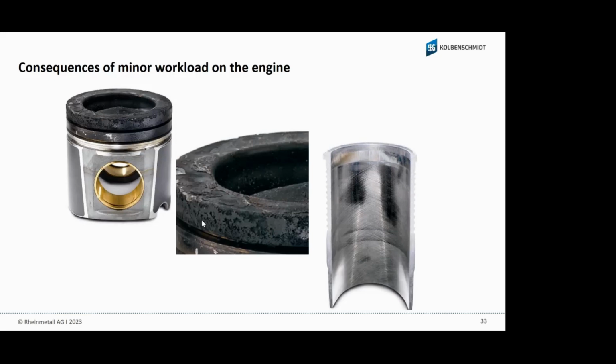And this is exactly the situation when they use an engine in a wrong condition, and the oil jumps up to the combustion, the oil is burned, builds up the carbon, and then we have also this polishing effect. And this is the biggest problem in the field. Much more carbon builds up on an engine with a steel piston, because a steel piston has a much higher temperature than an aluminum piston, and the oil burns quicker and builds up more carbon when oil comes inside into the combustion side.